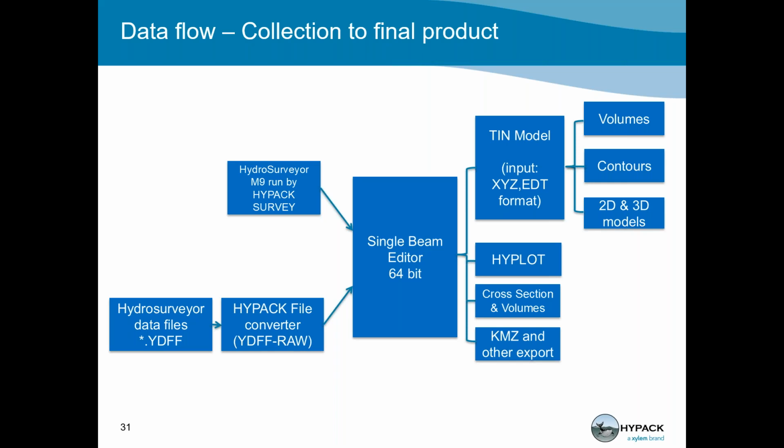From there on, you clean your data, you apply tides, or whatever you want to do with the data. Once it's edited, you can make a model out of it, that's what we call the TIN model. Or you can plot it, or calculate volumes, or do cross sections, or you can go straight into an export. Or you go further on and do contours, volumes, or 3D models. I'm going to show you this.